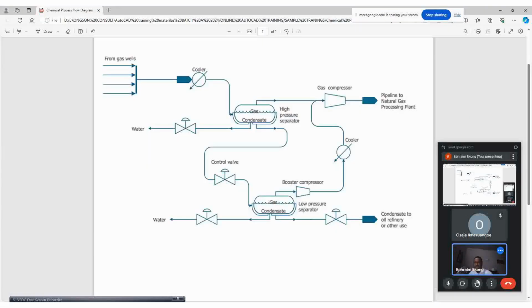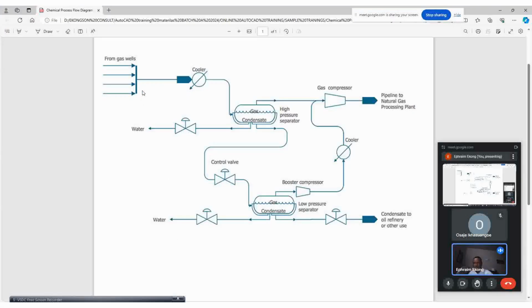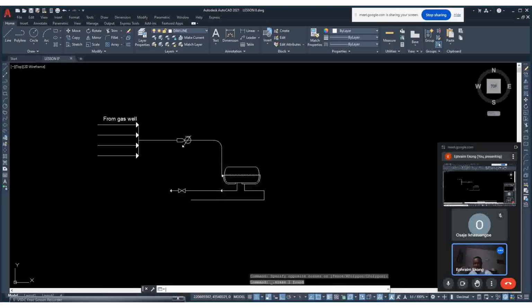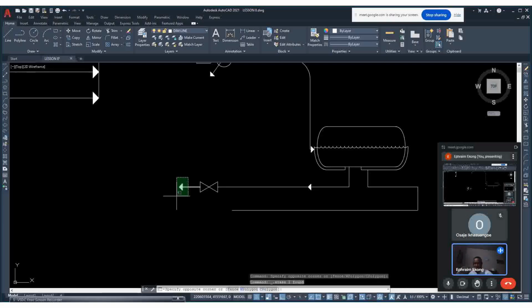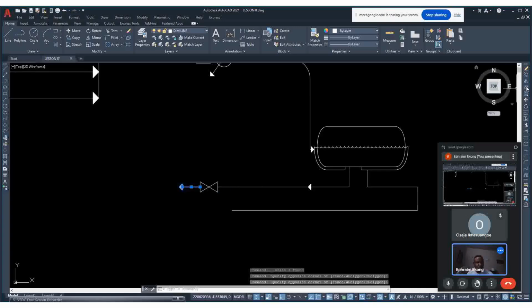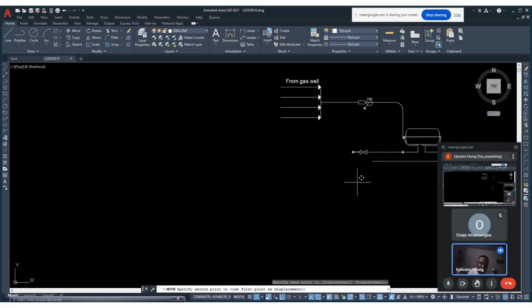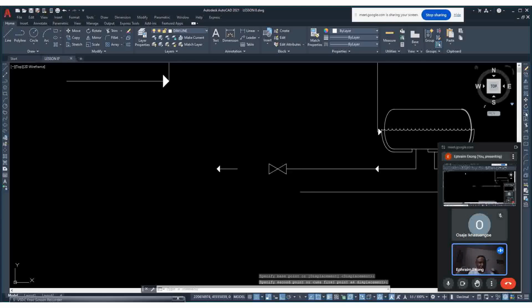So what next? This line is extended outward close to this point. So you have to shift it a little bit. Go to move. This is move. Then you move it. Click here. Then you move it this way a little bit. If you're okay, you click to stay. After that, go to extend and press enter and extend it.